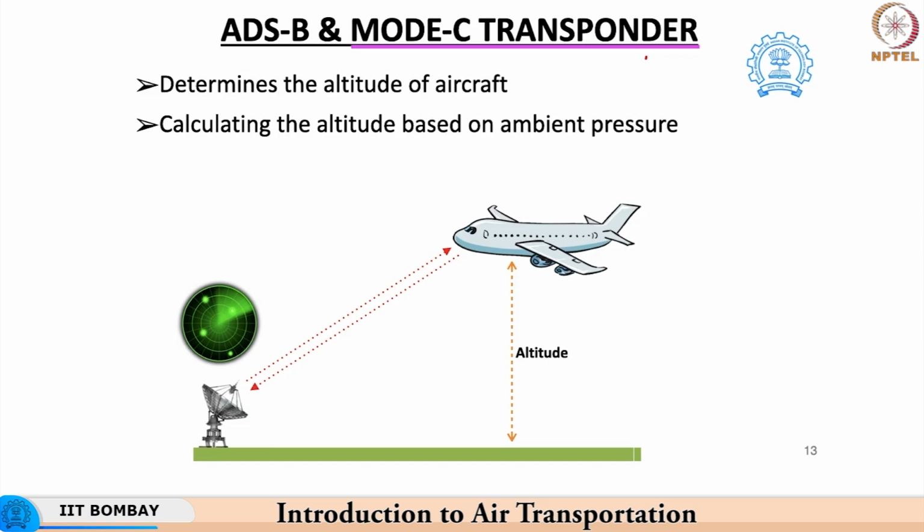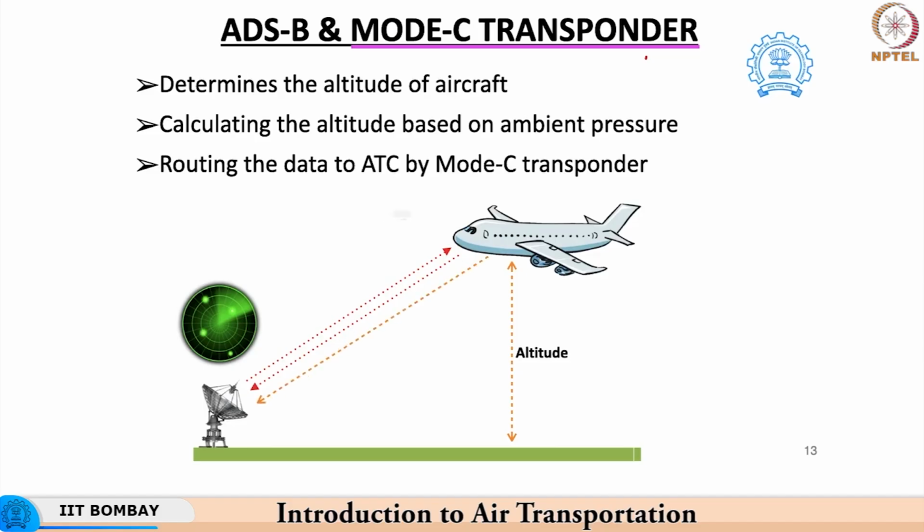So, in a nutshell, the ATC controller through the usage of a mode C transponder is able to obtain a more three-dimensional viewpoint of the aircraft positioning and is hence able to carry out the air traffic management in a more efficient manner.